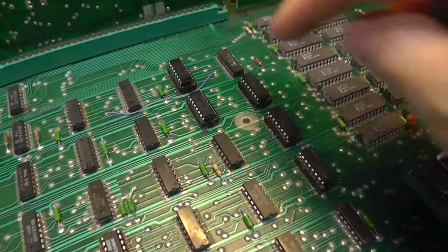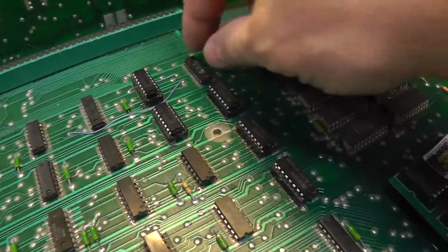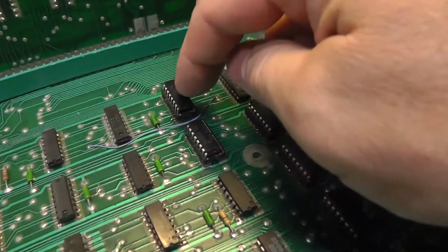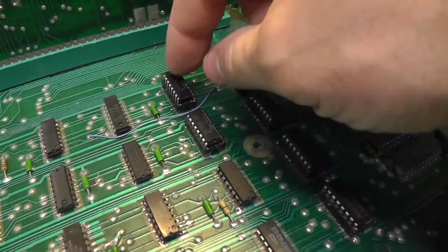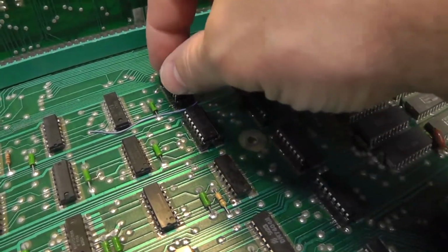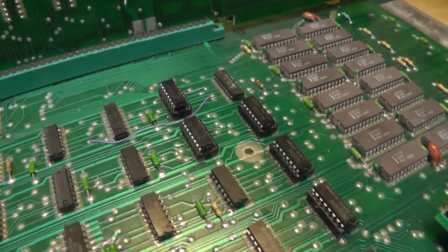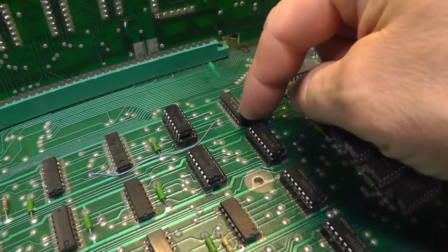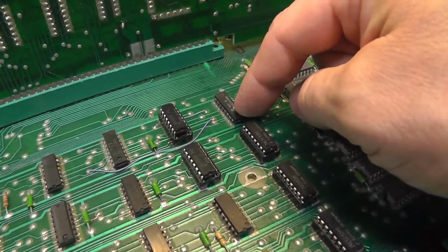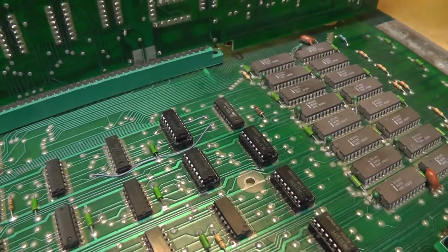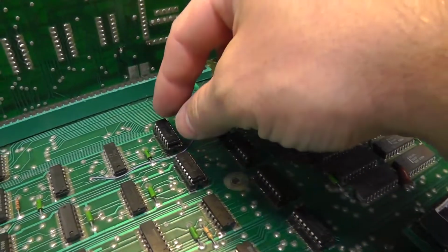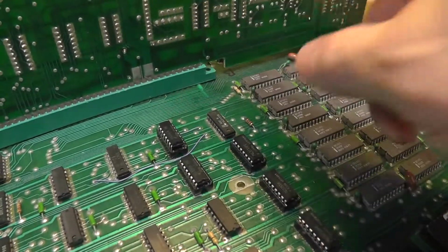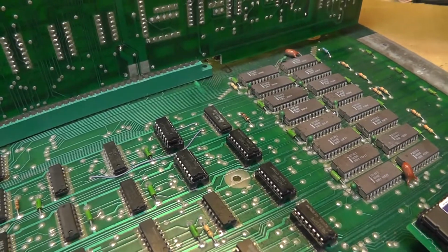So basically this chip right here, this multiplexer, is missing some of the video address lines, and it's probably because of a bad socket job on this chip here, which I might be responsible for. I'm not sure, I can't remember. Or it could be because this chip was removed as well, and it could be something bad on this side. I'm going to have to investigate what's broken or run jumpers on those lines.